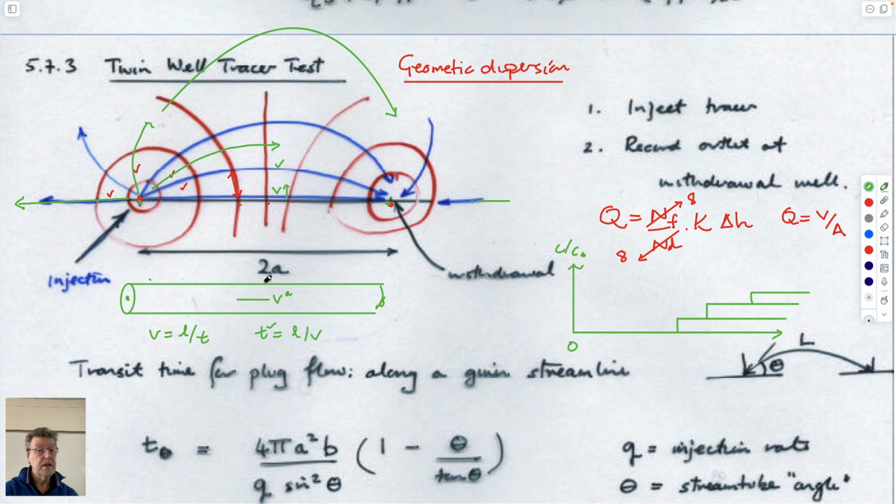And those would arrive. So even if you think about the travel in each of these stream tubes, if the travel within each stream tube was actually plug flow with no dispersion, you'd expect it to look like maybe this, halfway along. So if each of these stream tubes looked like this, and therefore dispersion was actually equal to 0, as we'd expect in the advection dispersion equation, the residence time distribution curve that you get still has some dispersion in it, even though there's no dispersion in the system.